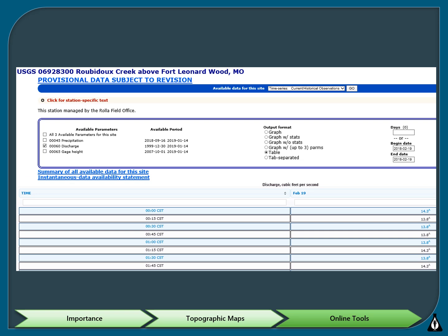As a reminder, the discharge data available on this site can be used to report on the discharge data sheet only if the gauge is located on the same stream within a half mile of where you're taking discharge, with no inputs or outputs, meaning no tributaries coming in or leaving the stream. So if you report using this data, you have to report the gauge station number with your flow data.